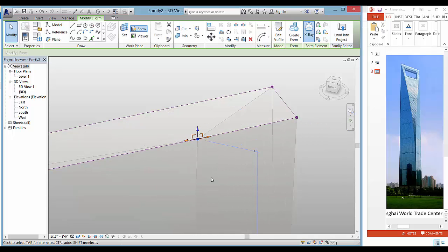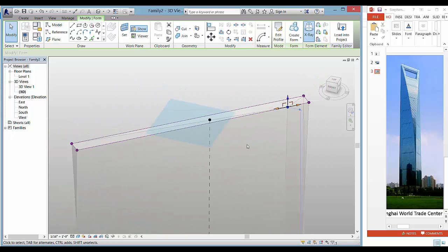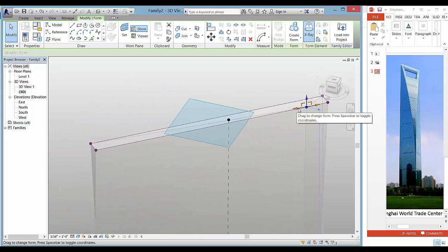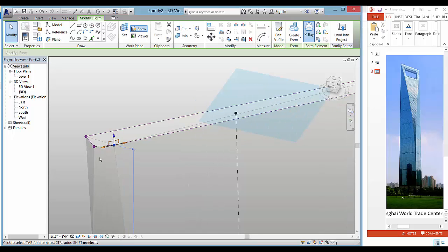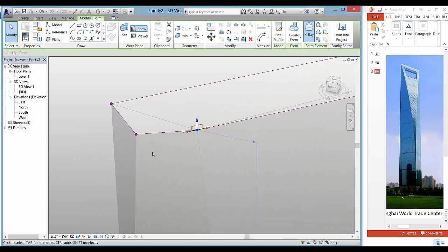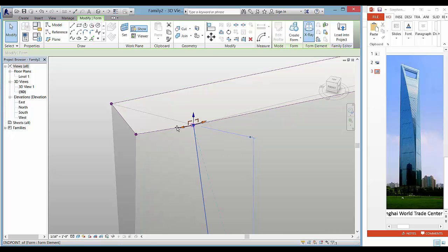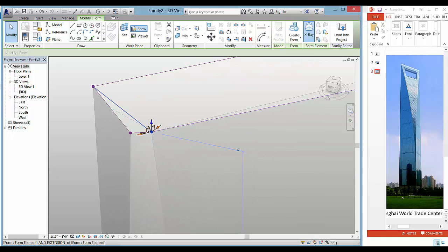And what happens is it creates this arrow that's pretty straight along that top edge. And now I can continue to use the arrow to pull my mouse towards the left. So I'm creating another edge, but it's not exact, so over here at the corner I have to do a little bit of playing around with that small dot there, grip, to pull it back into place, because I'm basically creating another profile, another edge.